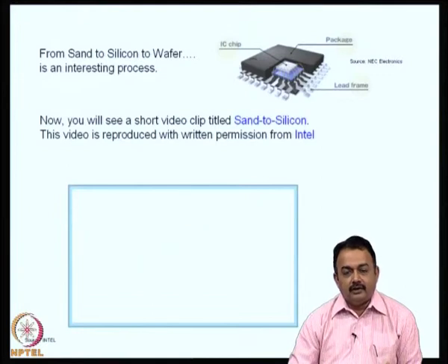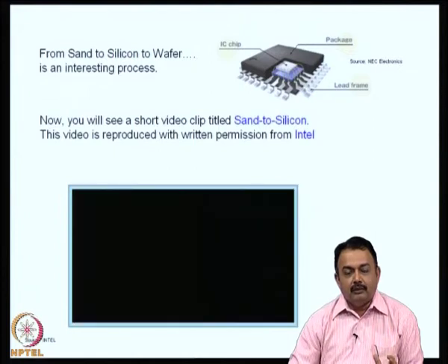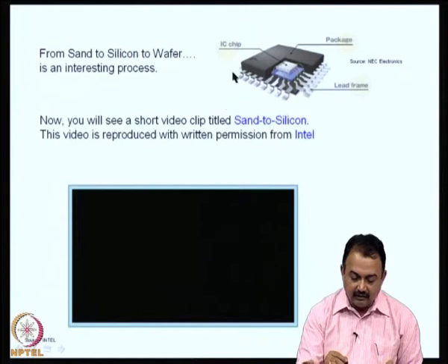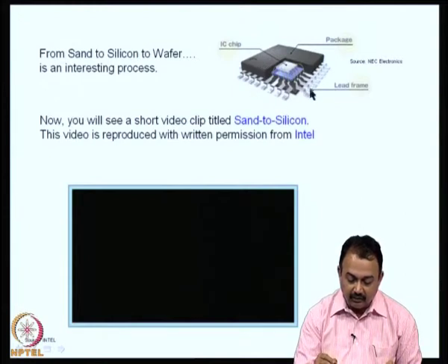So, as you have seen here, this is an excellent video which tries to impress upon us how the utilization starts from using sand to manufacturing high grade electronic grade pure silicon, and then that is converted into a wafer, and from the wafer how a singulated die like this is a single die is formed. And you can see in this picture here very clearly how the wire bonds connect from the bond pads of the die to the lead frames, and this is the package.